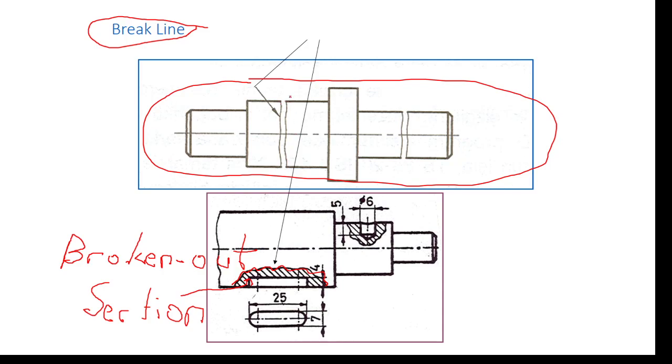They say that the intermediate part of a long object has been omitted in this projection. Whenever the entity is very long, to fit its image in a limited working space, and the geometry and size of the entity is the same from one end to the other, geometry is not changing, size is not changing, so why not?